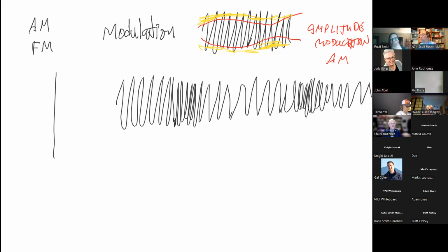Now, it's also true that what we end up looking at in the real world is that most noise that's naturally generated, such as thunderstorms making lightning and things like that, most noise is AM. Most noise is not FM. FM is kind of one of those things that's not a naturally occurring thing. And on top of that, when we get into a radio, when we demodulate it, we kind of cap off the maxima, and we basically just end up with a frequency of a constant amplitude.